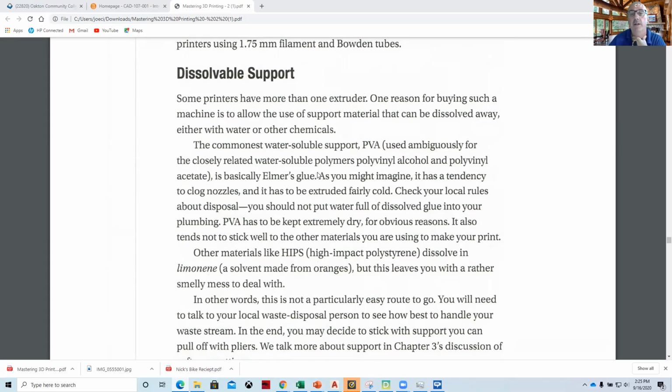When we use some of the Stratasys Dimension 3D printers, we take the parts out of the printer and put them into a tank that will have either water or a mild acid in it that will then dissolve the support.